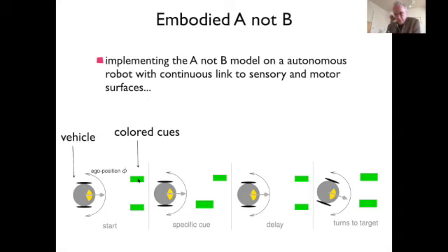I think we had a yellow thing. So it orients to something yellow by just filtering out the yellow from its camera. It's a very simple form of segmentation based on color. And we organized the whole task by varying how large the object is in the camera plane. That was done by moving stuff that we want to be large close to the robot. So for instance, the cue, when you tell the baby or the robot here to orient to one of those, the cue is just put close to the robot. We rigorously imposed the delay just by having a timer, so it wasn't done autonomously.